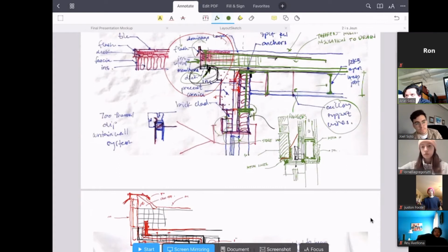Is it a 2x4? Is it a 2x6? Is it a 2x8? Whichever that is. But let's say I put a 2x8 or a 2x6 and it clears out that space, that's perfect, because over here I can put a smaller piece of metal and continue it up, and my drywall can come and stop right here. And then my ceiling will stop right there.